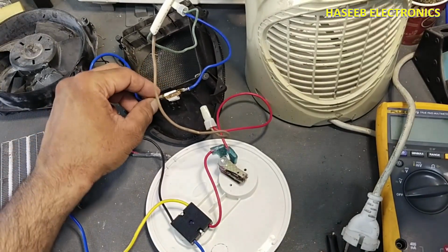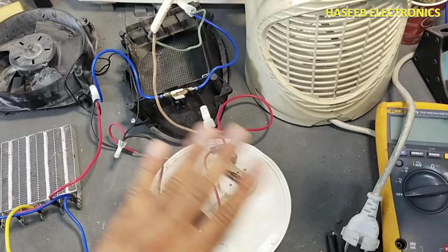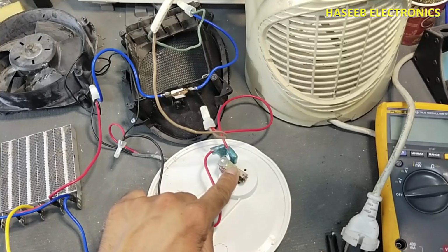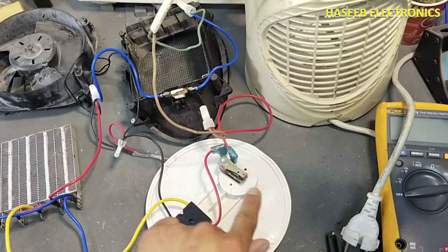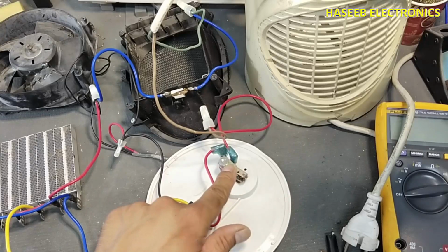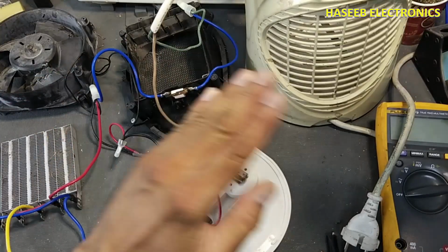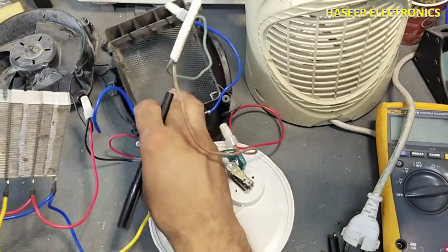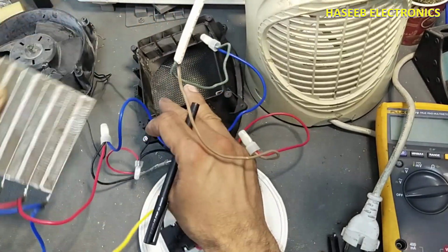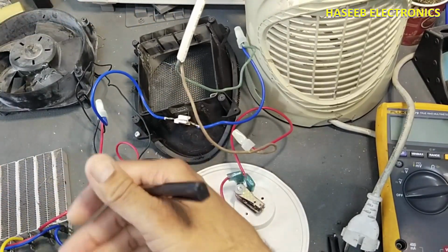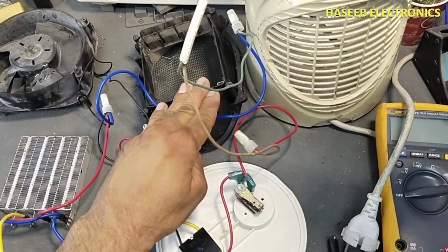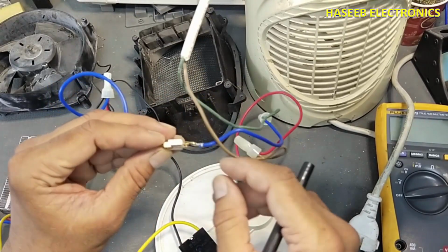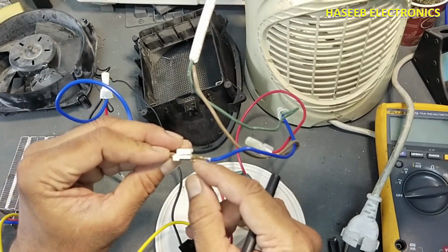At a specific temperature it will turn off the system. That is for protection, and this protection is much higher than this one. In any case, if this thermostat cannot operate or there is any obstruction, the air is not blowing, and this heating body, it is fitted in this plastic here and it is heating up continuously, so it can melt this plastic, it can cause a fire. At that time this protection will enable and it will turn off the system from this contact.